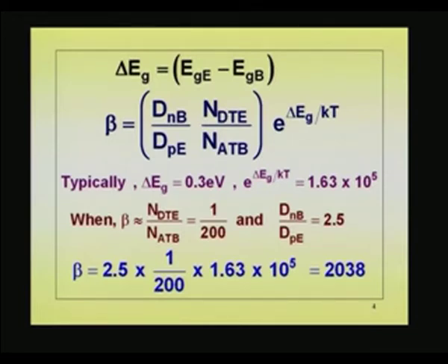In a conventional bipolar junction transistor, even though it is silicon emitter, silicon base, the band gap in the emitter is slightly smaller than that of the base, which actually can lead to a beta which is lower than what you get. You have ND in the emitter and base a big ratio, but this brings that down if delta Eg is negative.